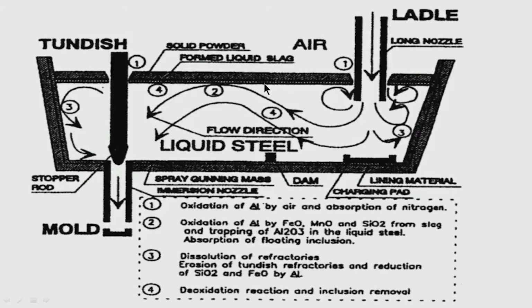One, just at the top of the liquid steel, a basic slag which is used for absorbing the alumina oxides which are forming and trying to come to the top, and on top of the basic slag we have another constituent known as rice husk. It is a good insulator, it does not allow the liquid steel temperature to fall beyond certain limits. Now at this point